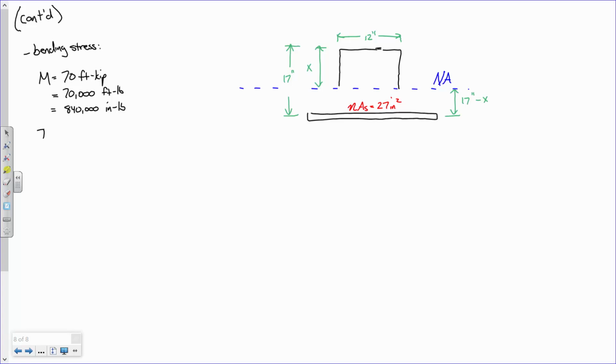It's kind of tough. Okay, so just writing down a couple other values. The transformed moment of inertia is 4067 inches to the fourth. And what was x? 6.781. Okay. Now, I'm throwing this bending stress calculation in there just so everybody gets accurate values. So now that we've done the transforming component of it, we can use sigma equals My over I. We've got to be a little careful with the steel component.